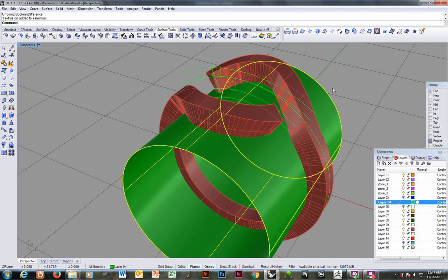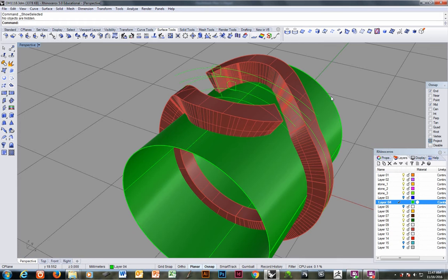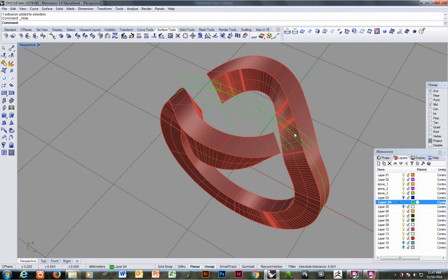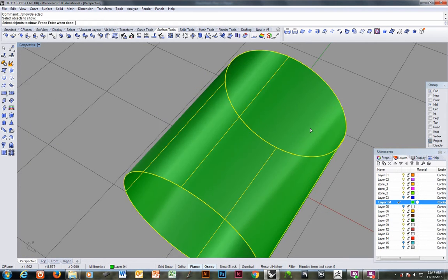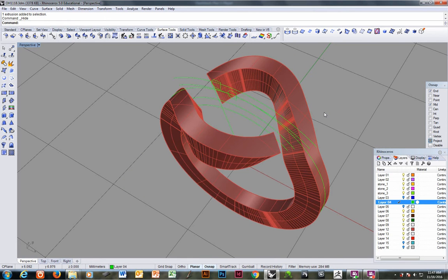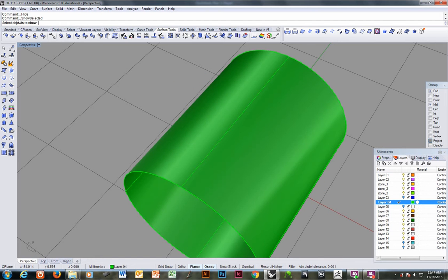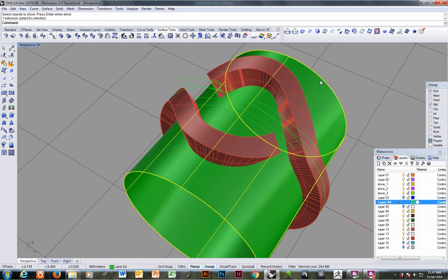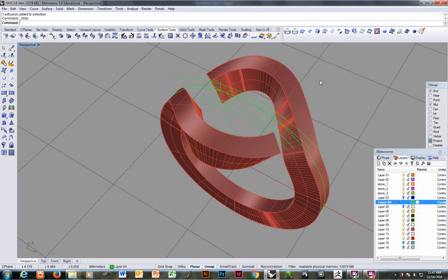So I'll leave it there. But I will keep this on my hidden layer. Let's see what you have on your hidden layer. Nothing. Good. I'll hide that. You know how to hide? No, I don't know. If you want to hide, you just select something and hit Control H. It's still in your file, it's just hidden. If you want to see it again, you hold down Control Shift H, and Rhino will show you all of your hidden objects, and you select which one you want to show again. Okay. And it's back. It's just a fast way to get things out of your way.